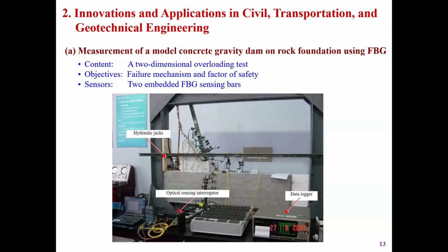We put the sensors in a tiny solid tube, like my finger. We drill a hole inside and put the tube into it. We put the fibers, similar to strain gauges, FBG strain sensors, on this side, in case there is any bending.